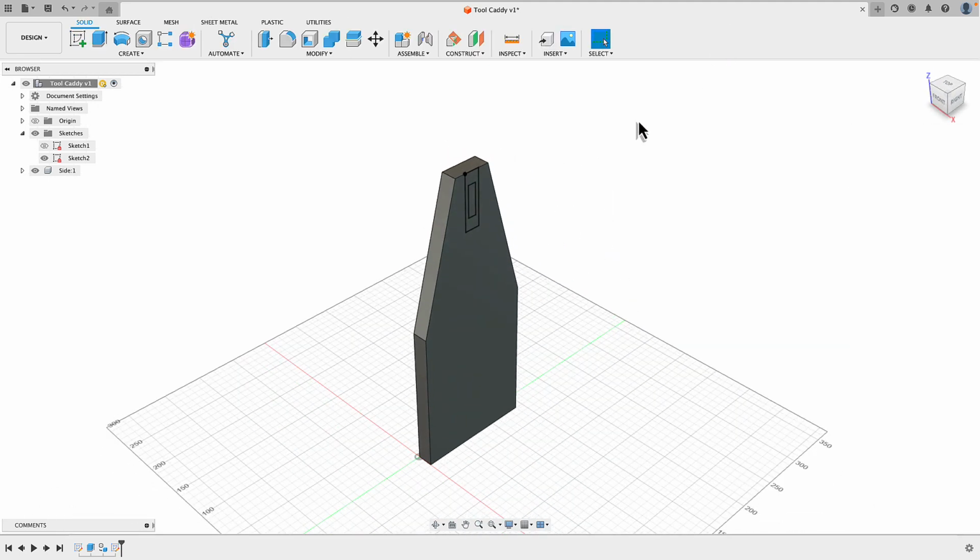Okay, so the first thing we'll do is create the geometry for our handle. Now overall the handle is going to be 400 millimeters long, but that also includes the tenons, which are going through this 19 millimeter thick timber as well. So doing a little bit of mental arithmetic, that means our handle is going to be 362 millimeters between these inside faces, or another way of putting it is the inside faces of each side will be 362 millimeters apart.